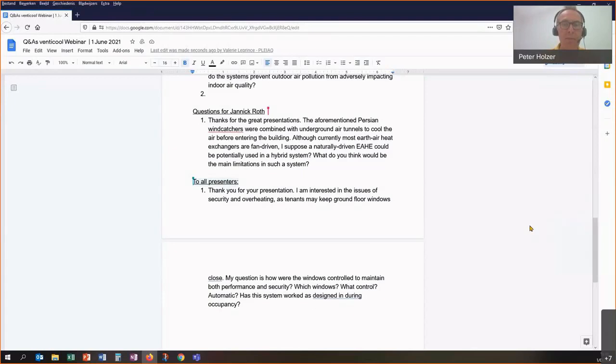It's quite the same situation like Peter Foldbjerg mentioned. When you have a staircase and the air gets warm in the staircase, you're happy if it is pulled out directly through the roof window and not pulled through your sleeping room. And so it's a good idea to have the earth tube heat exchanger equipped with a shortcut that discharges it without entering the house. So this was a learning from one of our projects.